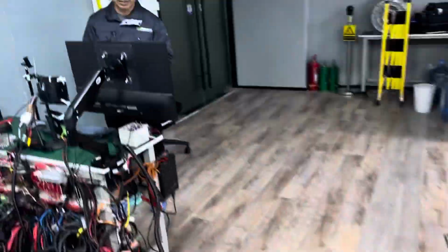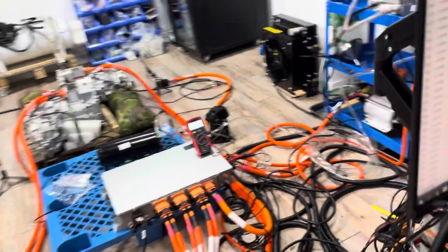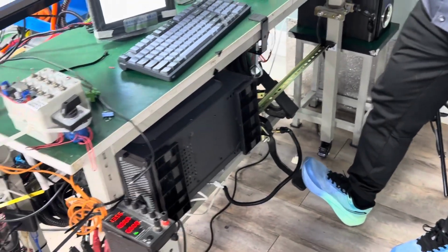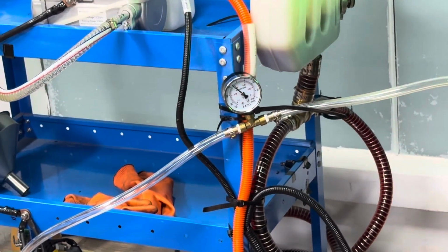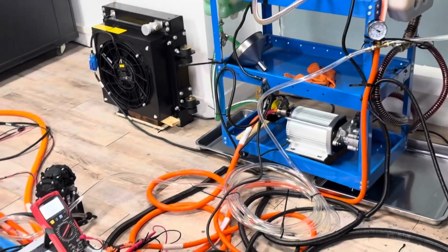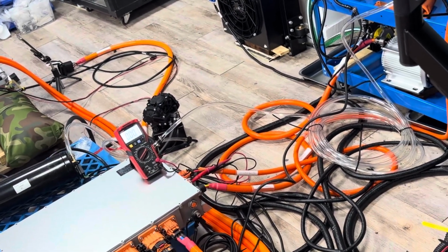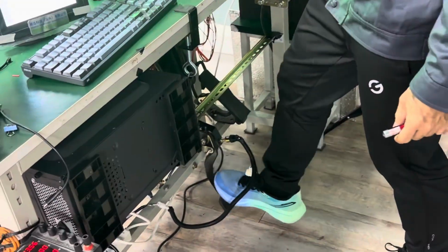And let's also test the vacuum pump start function. Now we can see the meter of the vacuum value. If I step on the brake, the vacuum level will drop one by one. When it drops to a certain level, the pump will start working to increase the vacuum level of the system. Stop already. If I step on the brake again,